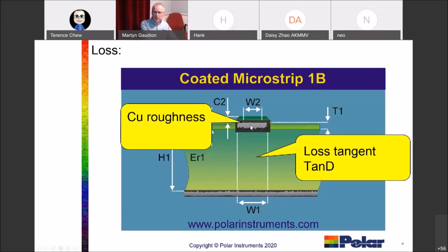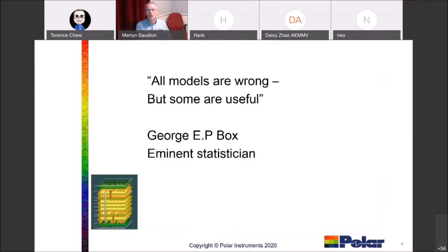If you had a foil like this, where you have this face and this face carrying the signal, then with the same copper foils, just having the signal on the other surface, by flipping the stack up round, you could reduce your losses, and you can model how that works by using the SI 9000. So modeling, we'll look at modeling.